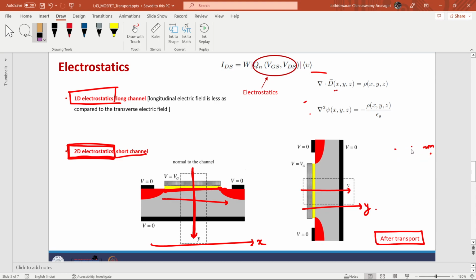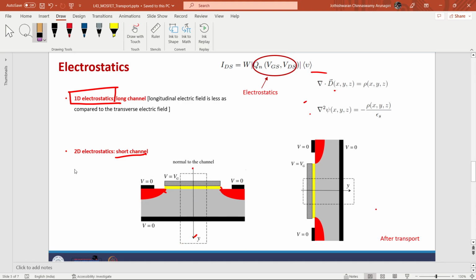So far, we have simply been saying that because of the oxide capacitance, C-ox, I have some charge accumulation, and that charge contributes to the current in the channel. That is what we have been stating. But for typical devices, I cannot model this entire interface using just one capacitance parameter. That is not a valid expectation. So there may be other effects also.